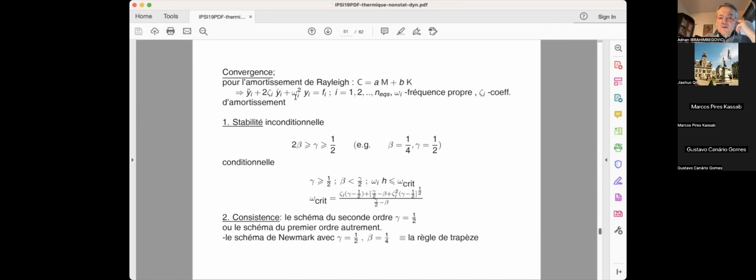Your stiffness matrix becomes omega_i squared, the diagonal matrix. And then damping, diagonalizing C, which has contribution from mass and stiffness, you call these coefficients 2 times psi_i times omega_i, times y_i dot. So psi_i are these damping coefficients that you want to choose.